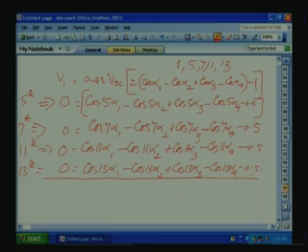So 50 times we have to calculate alpha 1, alpha 2, alpha 3, alpha 4 and V1, because as the motor speed increases, the fundamental amplitude varies in proportion to the speed. That means 50 steps are required, and 50 times we have to solve this because V1 is varying,